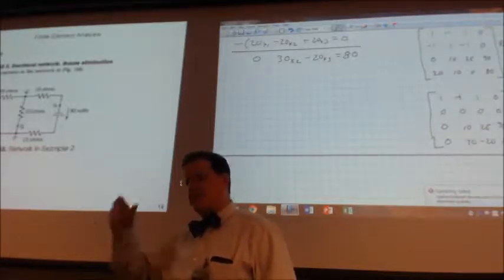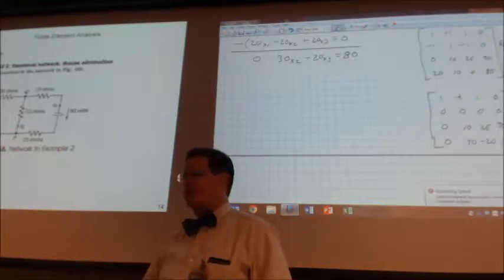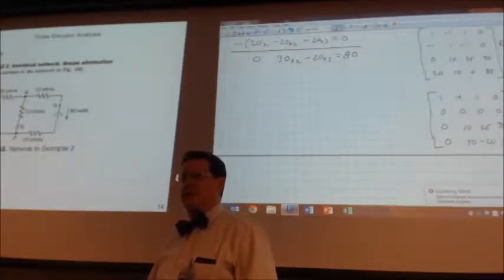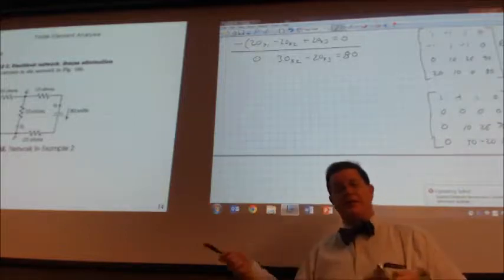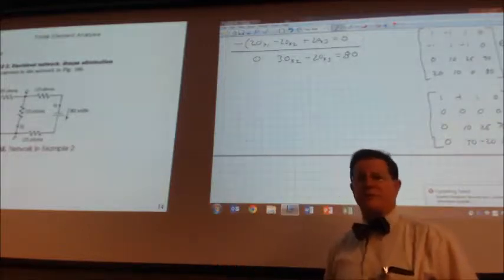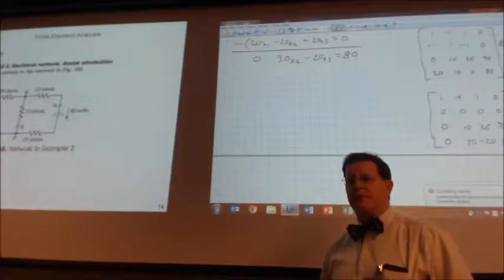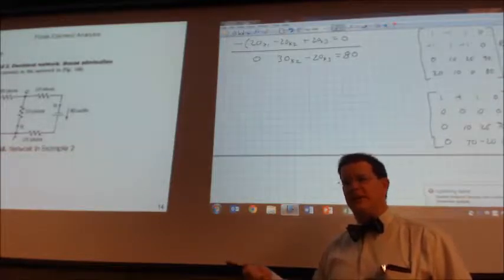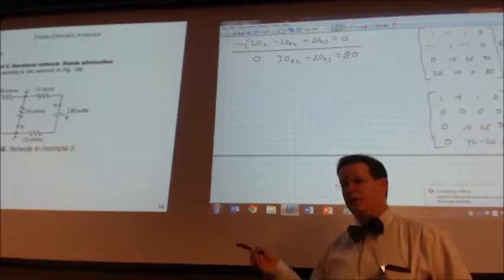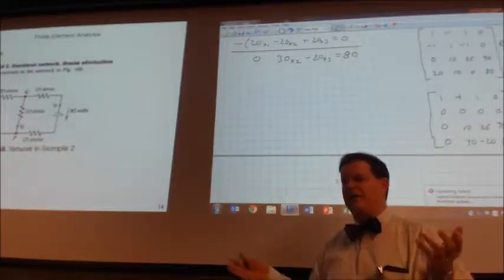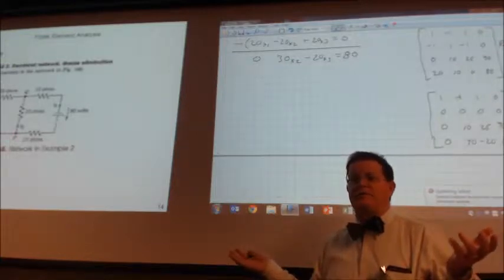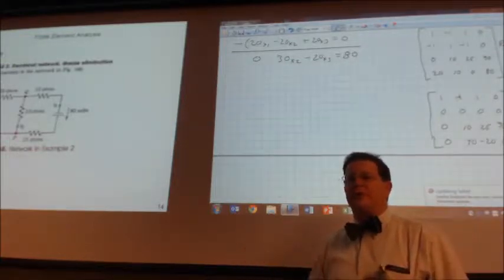And that comes from tensile testing and various other things to figure out what that's going to be in the various different directions. Because wood, like you said, we know that's not homogeneous. So you're going to test it in at least 3 directions, and you're going to get different values for each one because of the grain structure.